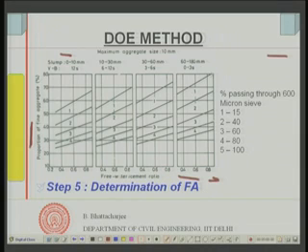So, it is a coarse sand. This line actually represents a very coarse sand. Next one, 40% passes through the second line. So, next one, this line, for example, corresponds to 40% sand passing through 600 micron, 40% sand passing through 600 microns.